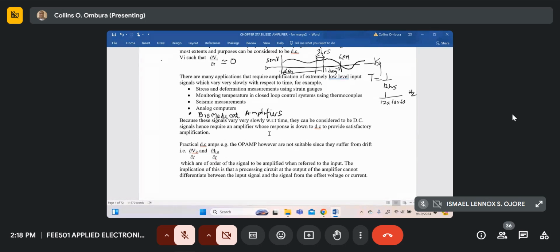Different types of resistors generate different types of noise. The highest quality resistors are those made from metal oxide, called metal oxide resistors. The cheap ones normally sold in shops, or used in your labs, are carbon resistors. Those generate a lot of noise.